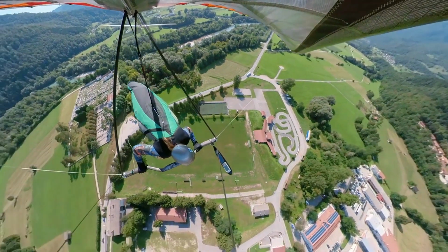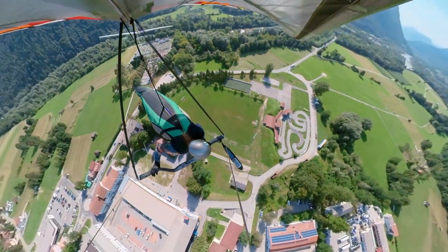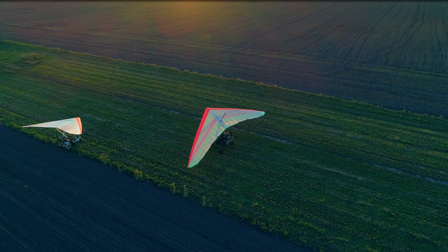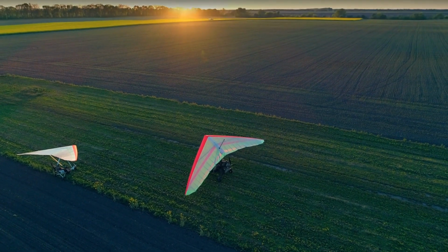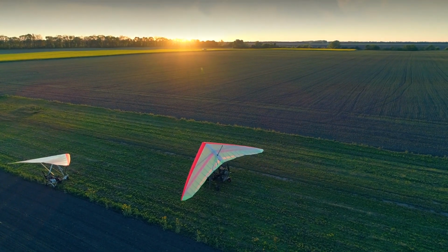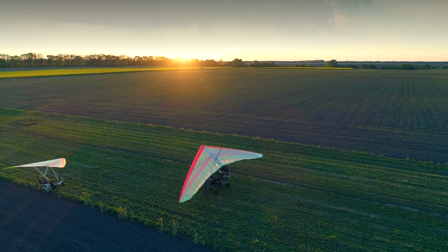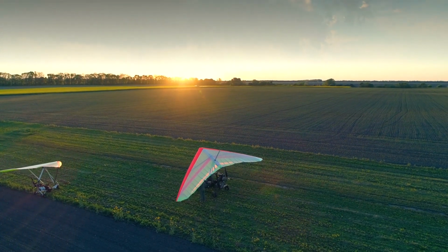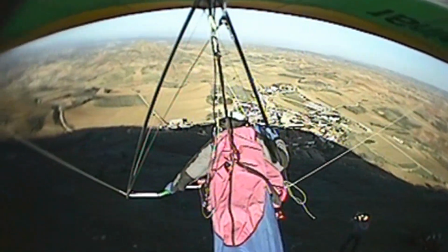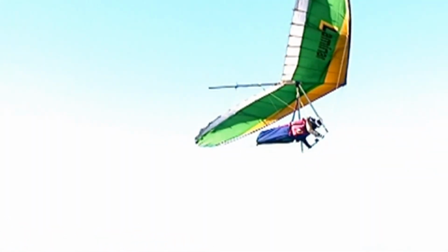The cruise AOA, the trim position of the control bar, represents the AOA and speed when flying straight in calm air. Planform refers to the shape of a wing viewed from above, ranging from larger, slower wings to smaller, faster ones. Aspect ratio, the wingspan divided by the average chord line, influences lift efficiency. Wing loading is the load per square foot of the wing, determined by dividing the total weight by the total wing area.